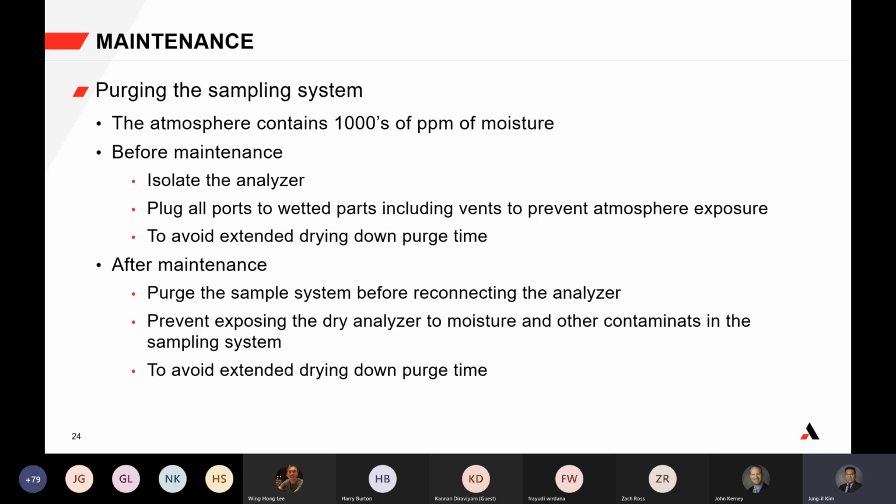If you roughly divide the 10 impurities that are in there, it's usually 7 or 8. It will roughly come down to a little bit more than 1 ppm of moisture. It can vary, but let's say 1 or 2 or 3 ppm of moisture you would expect in the best case plant nitrogen.